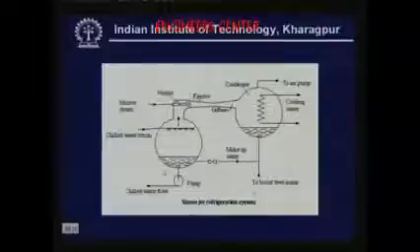These systems were used in the beginning in warships and breweries and so on. This is also used for providing what is known as vacuum cooling in food products. That means in the evaporator drum, which you have seen earlier, you can put the food products itself and take out the moisture from the food products using an ejector. When you are taking out moisture from the food products using an ejector, the food products get cooled. So this is the principle behind vacuum cooling. So this is the steam jet refrigeration system.